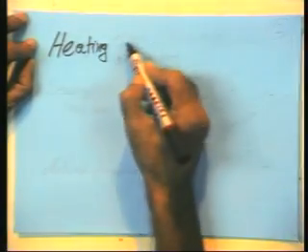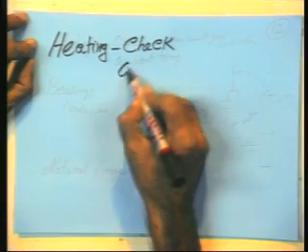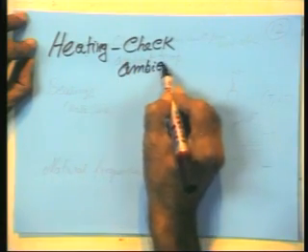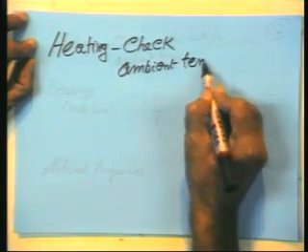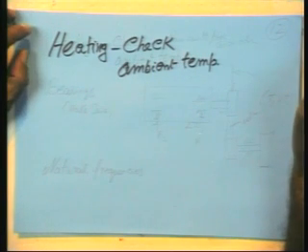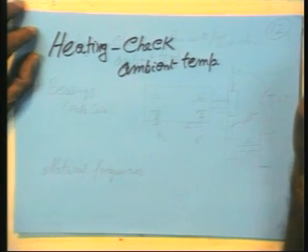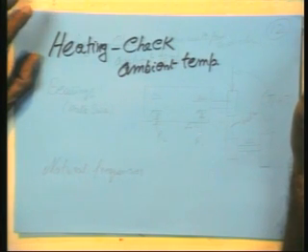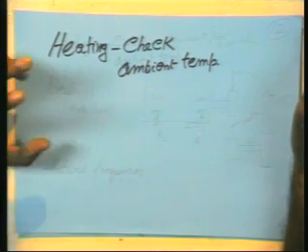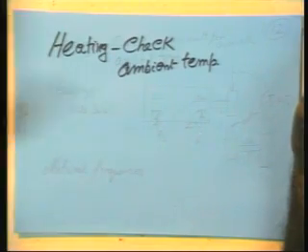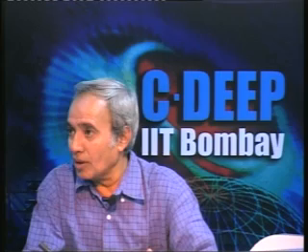Heating. Check. Remember, the ambient temperature matters in this case. If you are operating very close to some furnaces and all, you will have to worry about the ambient temperature. You may have to provide some fans, or motors come with and without blowers which will blow air through the motor in order to cool it. So your selection will depend on that. You may have to select a motor with a blower in case the heating is excessive.